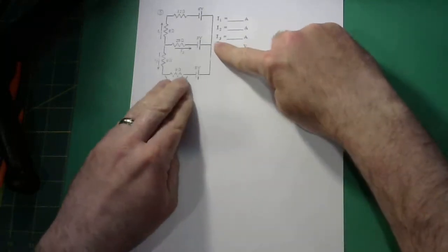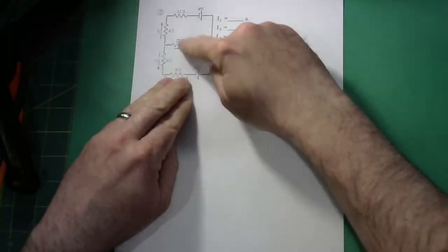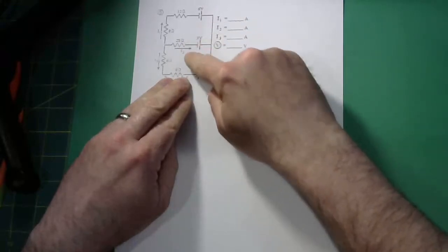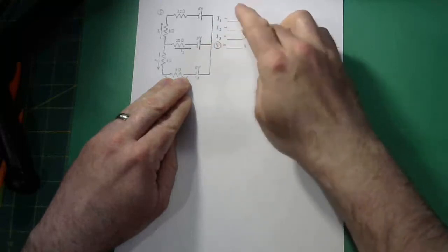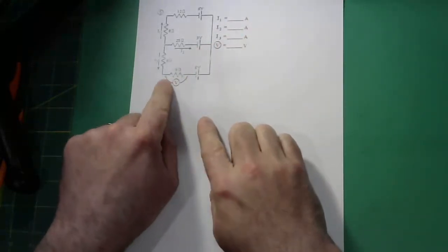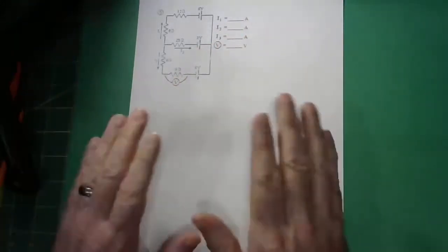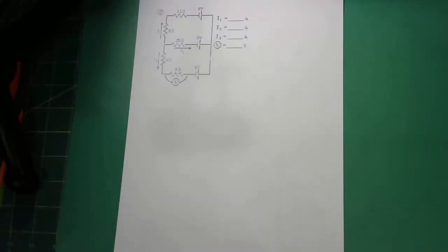Okay, so if I cover that up, we have all the resistors, we have all the batteries, and we just have 3 currents to solve for. We can get our 3 equations, 3 unknowns, solve for all these currents. Then I can just use Ohm's law to do delta V as IR here. So it's nothing to worry about. It's all good.